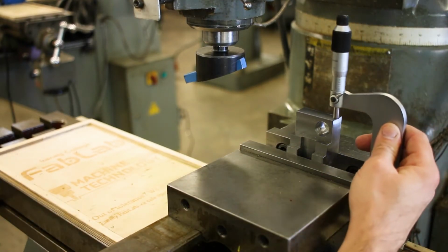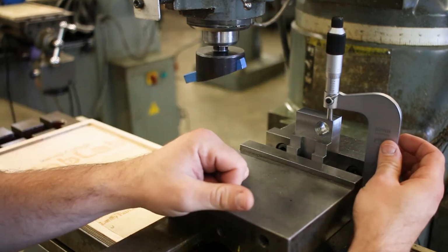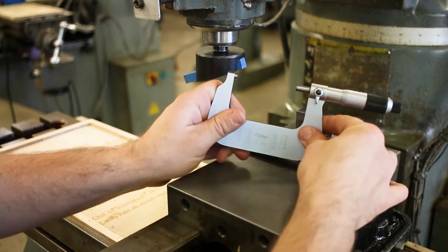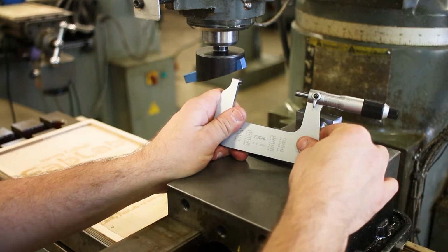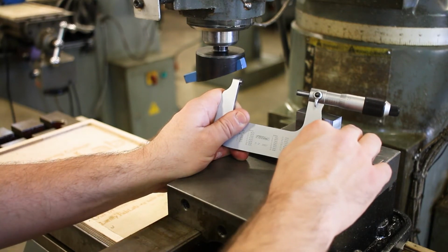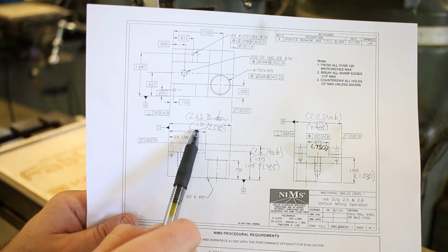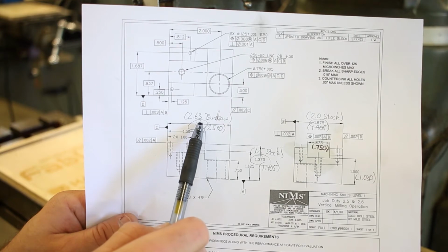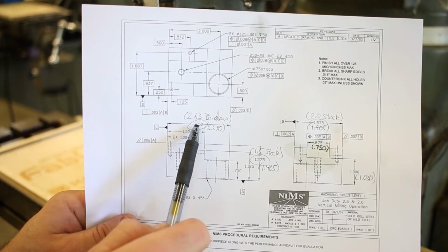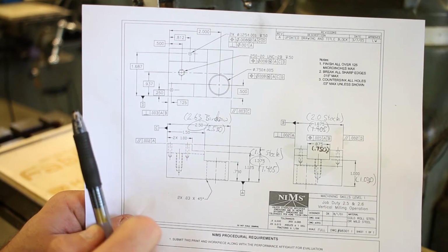Okay, let's take a measurement. Make sure that you're not measuring over top of the shims. Looks good right there. So what is that telling me? That's telling me 2 inches, 519 thousandths. So the final dimension here is going to be 2 inches, 500 thousandths. So 2 inches, 519 minus 2 inches, 500 is 19 thousandths, which is how much we still have to go. And because we're using a fly cutter, I'm going to take that in 2 cuts of about 10 thousandths.